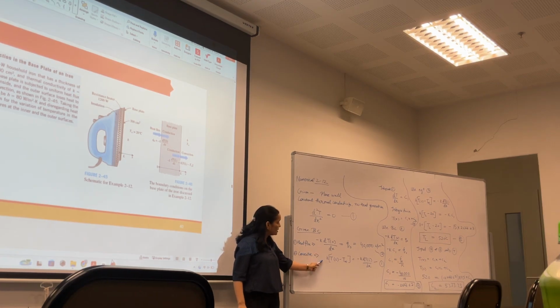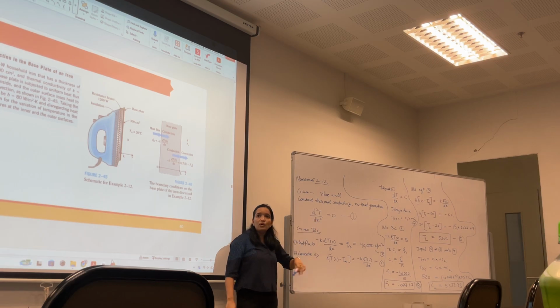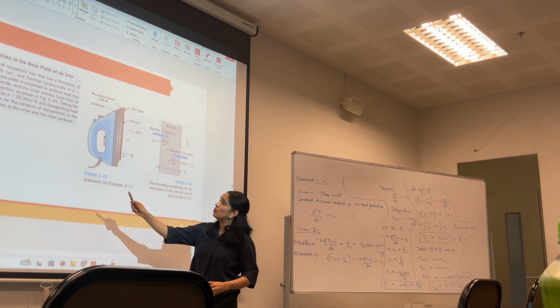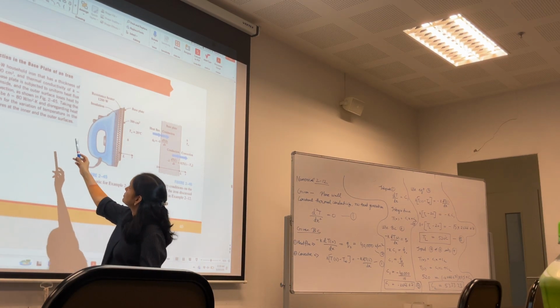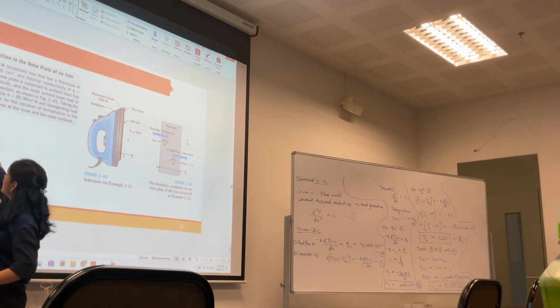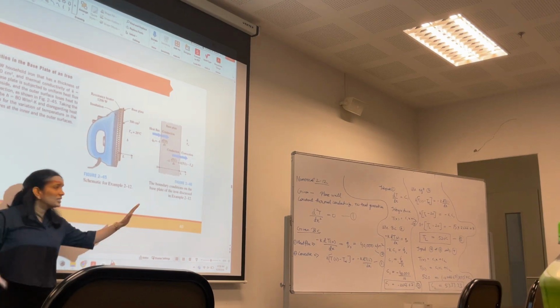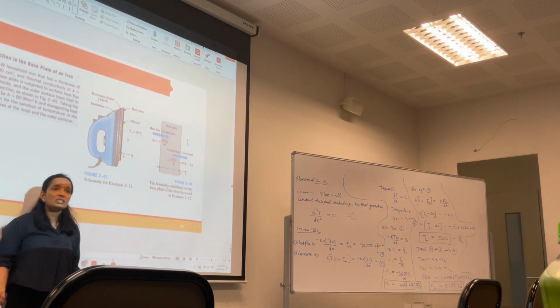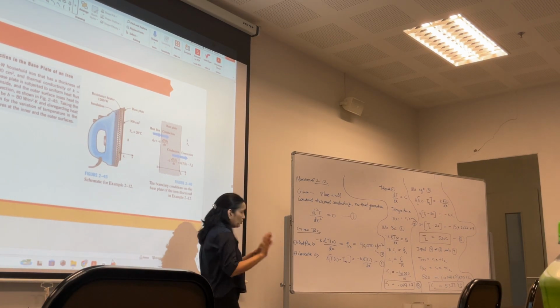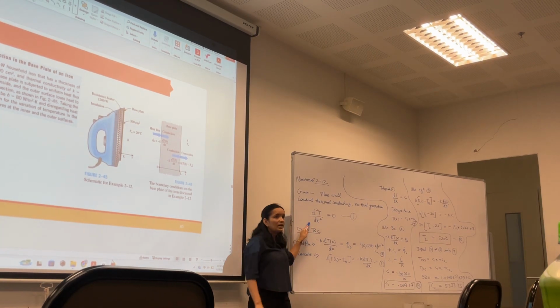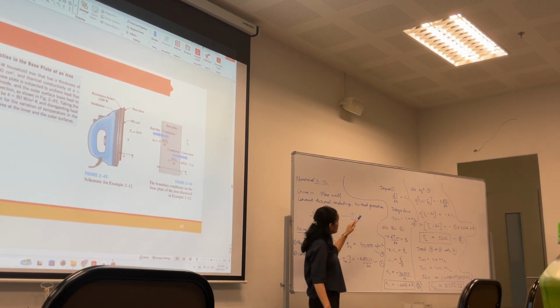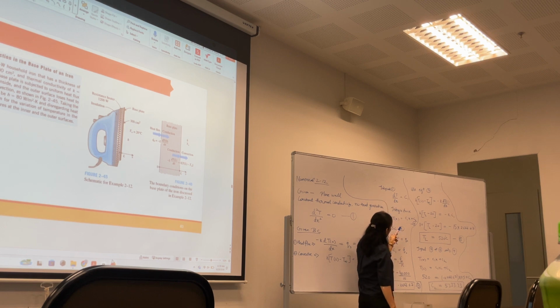So you have this given, this given, this given. Now you have to solve it. You have to find out, obtain an expression for the variation of temperature in base plane. In this case, you have to obtain an expression. Okay? So how will you solve? You first start to integrate it. You integrate it once, this comes, integrate it twice, this comes. Okay? Now you utilize the boundary condition in order to get one expression.